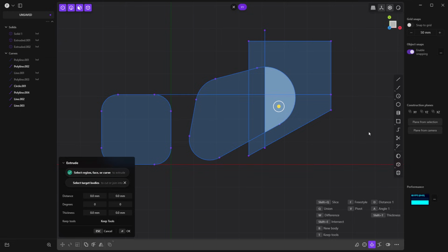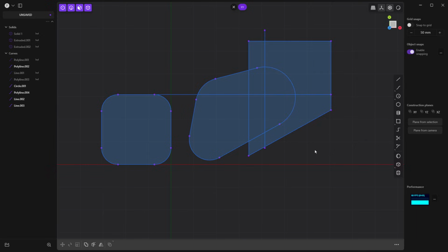And again, this is just by using a couple of these shortcut keys. Control while you're dragging will let you have that snap option. Tapping Shift will give you those extensions. And also using options like Move and Freestyle or Move and Pivot Point can give you the control that you need to make sure all these curves are sort of lining up how you would expect.